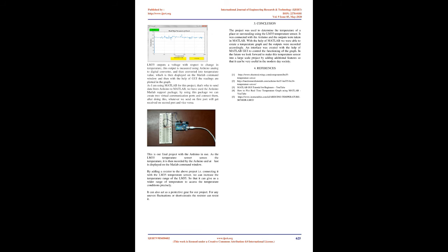As I am using MATLAB for this project, to send data from Arduino to MATLAB, we have used the Arduino MATLAB support package. By using this package we can create two virtual communication ports and connect them. After doing this, whatever we send on the first port will get received on the second port and vice versa.